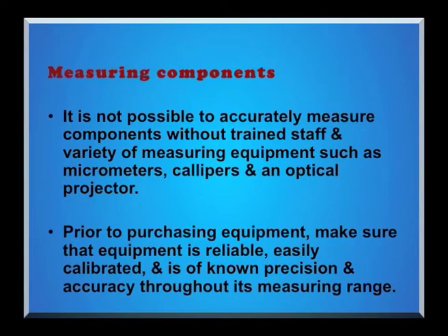Now third one, that is measuring components. It is not possible to accurately measure components without trained staff, and a variety of measuring equipment such as micrometers, calipers and optical projector. Prior to purchasing equipment, make sure that equipment is reliable, easily calibrated and is of known precision and accuracy throughout its measuring range.